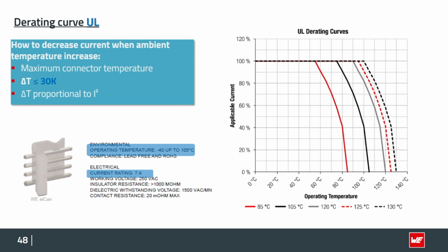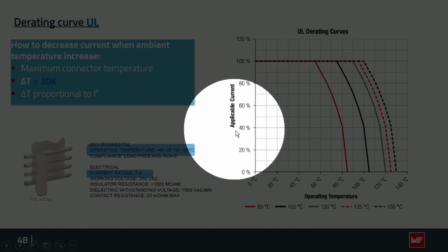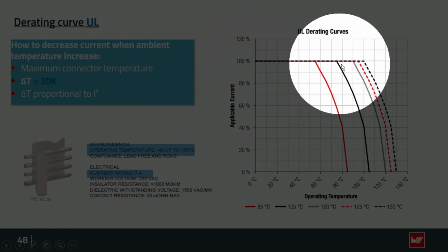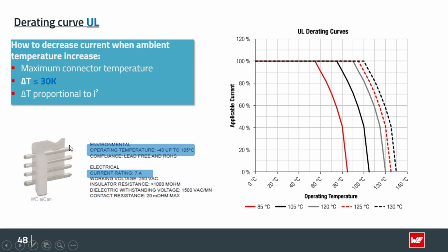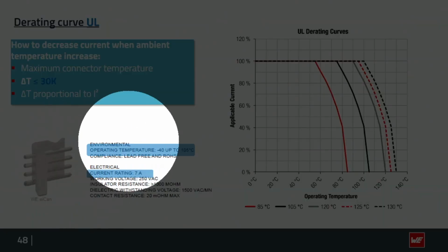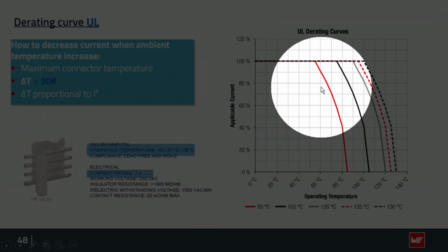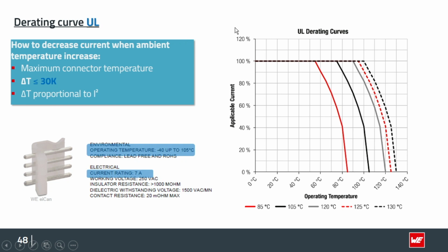So if you're looking at this kind of derating curve, you maybe wonder why this is flat on the top. It's just because of the cable which can be connected here. The cable in this square is limited in its amperage, and therefore the line was cut here. Normally, of course, you could draw this completely to the top.